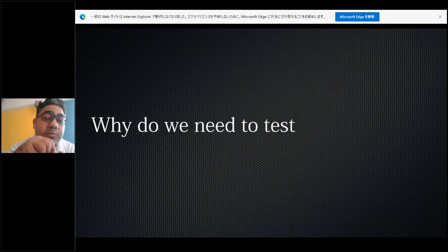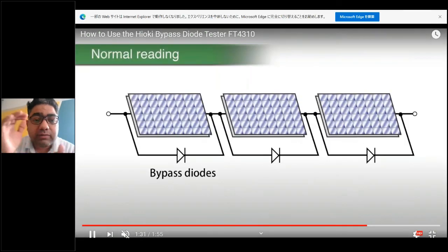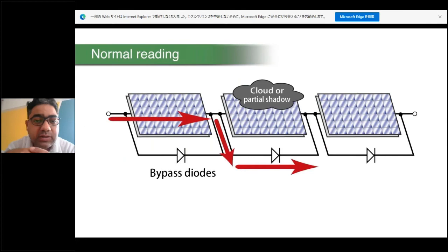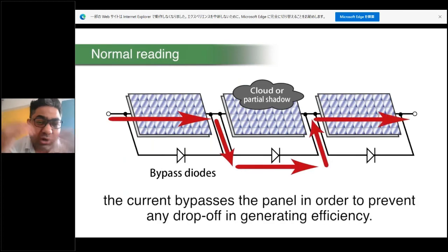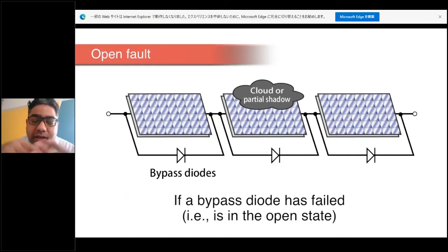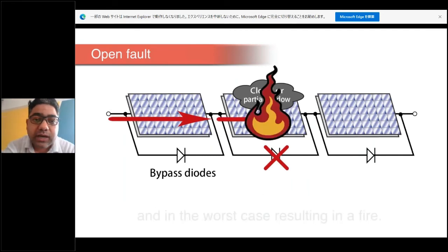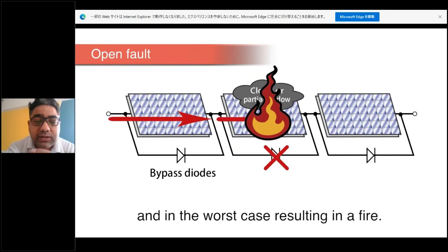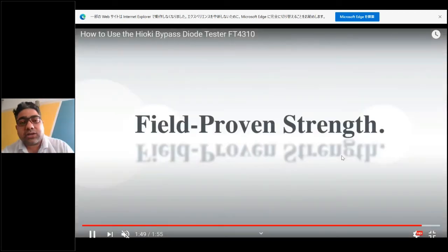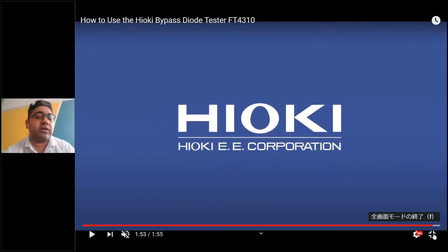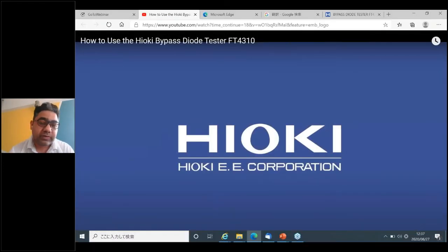Why do hotspots come up on our panels? And to detect that hotspot we use lots of technologies, imaging cameras, right? But what is the use of that? If we are able to detect that hotspot, this already means we have lost power, and in terms of power, we lost money. If that hotspot comes, we cannot do anything. We need to replace the module.